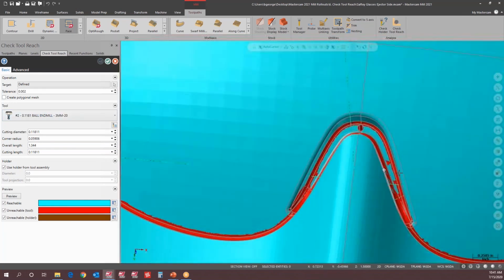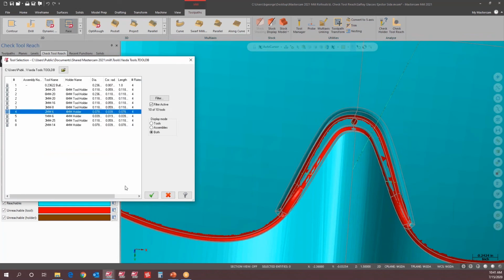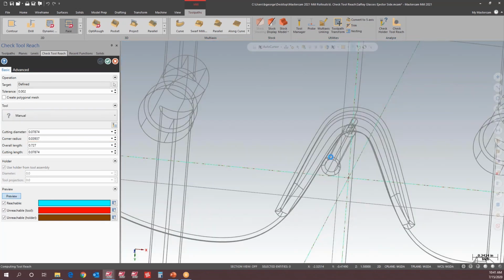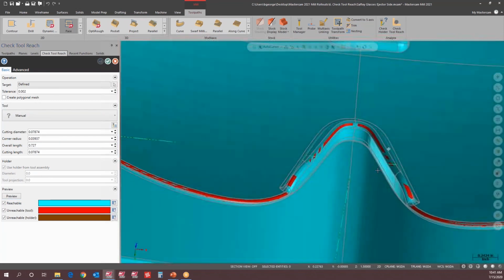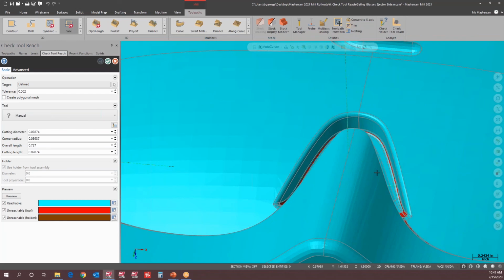So what do I need to do to basically finish this nose piece? Well, I think I can use, let's try a 2mm. Again, I rounded it off a little too much, being too accurate there. So a 2mm will pretty much finish this whole thing. So this is how I figured out what I needed to use before having to do any toolpaths.